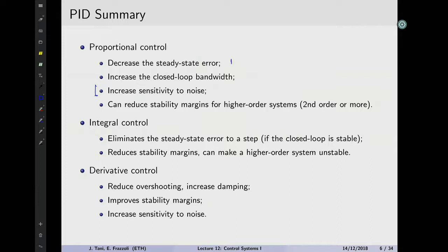But even with the proportional part, which can stabilize a system and provide decent performance, it still cannot remove the steady state error. As you increase the proportional gain, you will reduce the steady state error, but you always have it. Therefore, we saw that if we add an integral part, something you can imagine as keeping track of the history of the past, then by keeping track of the history of the error, one can compensate if there is a constant tracking error.